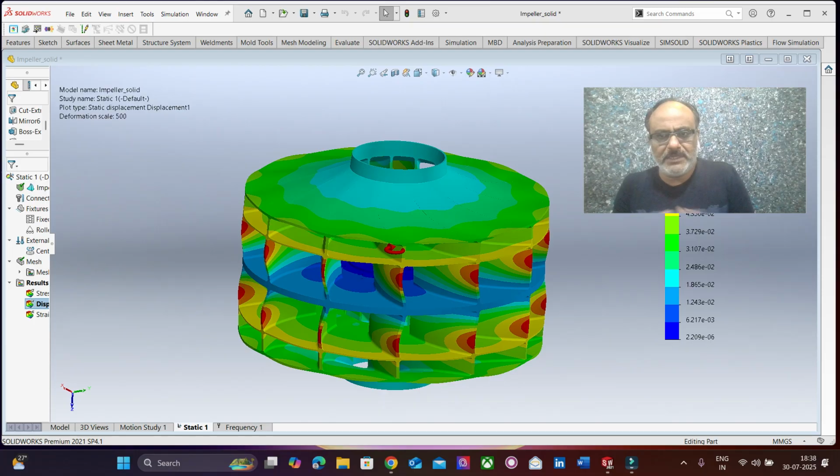All of this depends upon the type of model, the system that you are working on. Here it is a completely metal-based structure, and these are elastic in nature, and there is absolutely no plasticity occurring here. So for these kinds of structures we go for either Drucker-Prager or von Mises.